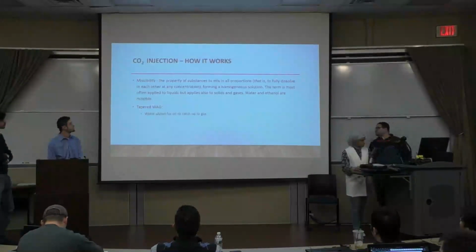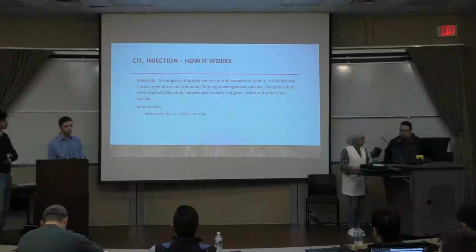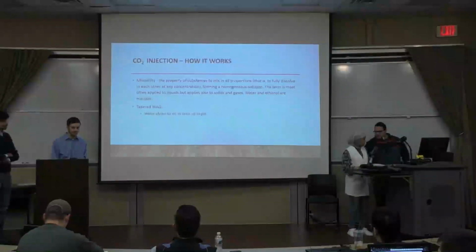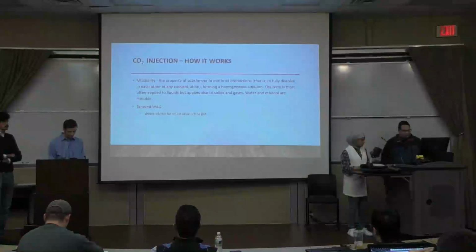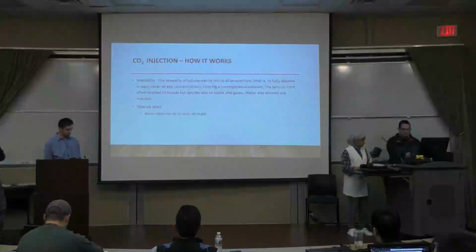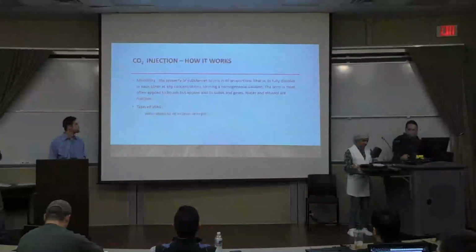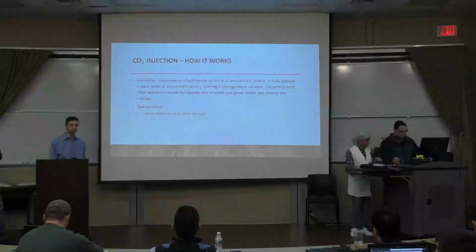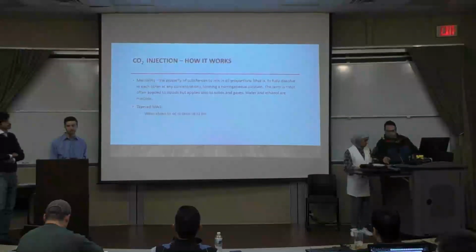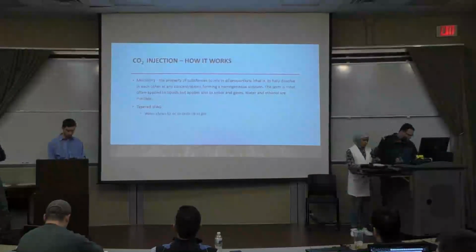First off, for CO2 injection, I'd like to talk about miscibility, and that's where fluids can usually just mix very easily. If CO2 is injected above the minimum miscibility pressure, interfacial tension effectively disappears, which lowers your viscosity as well as improves your mobility.